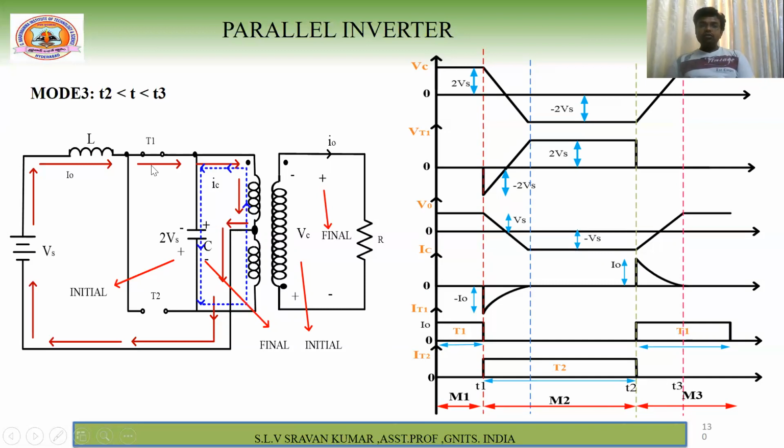So now once you give the triggering pulse to thyristor T1, how will the current flow again? This plus Vs, inductor, this transformer upper primary winding, and to line. Now the initial voltage polarity is this one. Because the current is flowing again like this, again some of the flux linking will be like here. So therefore, your capacitor will charge to a voltage of plus 2 Vs.